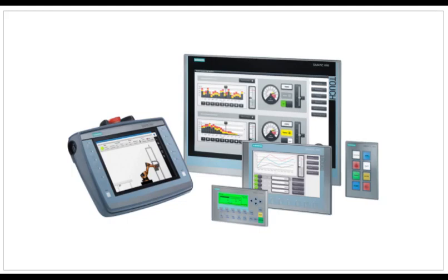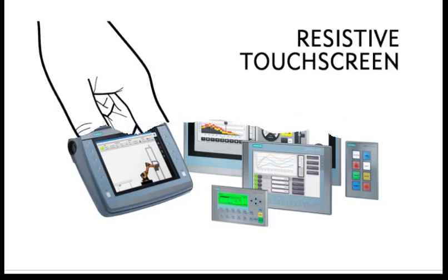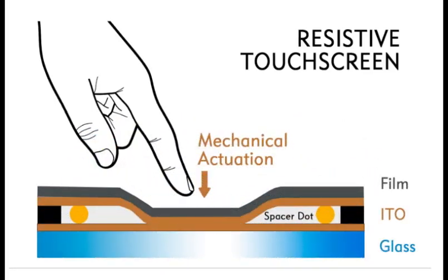Resistive touchscreen. 5-wire resistive touch is the most widely used touch technology today. A resistive touchscreen monitor is composed of a glass panel and a film screen, each covered with a thin metallic layer, separated by a narrow gap. When a user touches the screen, the two metallic layers make contact, resulting in electrical flow. The point of contact is detected by this change in voltage.